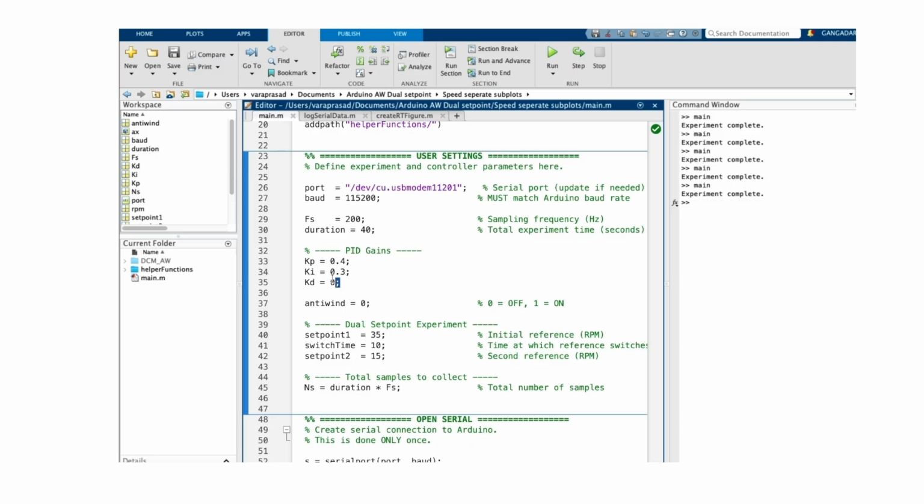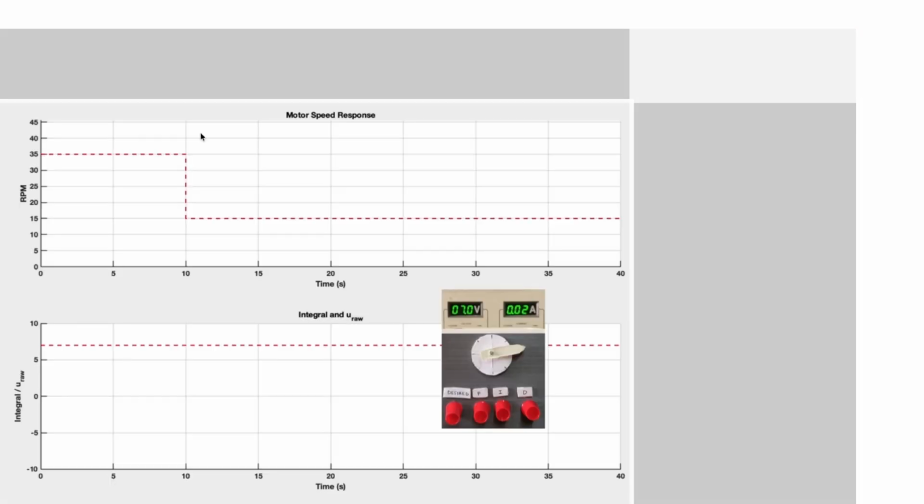We want our motor to run at 35 RPM. However, the motor that we are using has a limit of somewhere around 21 RPM. So, of course, the set point here is more than what the motor can do. Here is where we will face the windup issue. After 10 seconds, say we realize that the reference is too high, and then we bring it down to 15 RPM. Now, let us see how it affects the outputs.